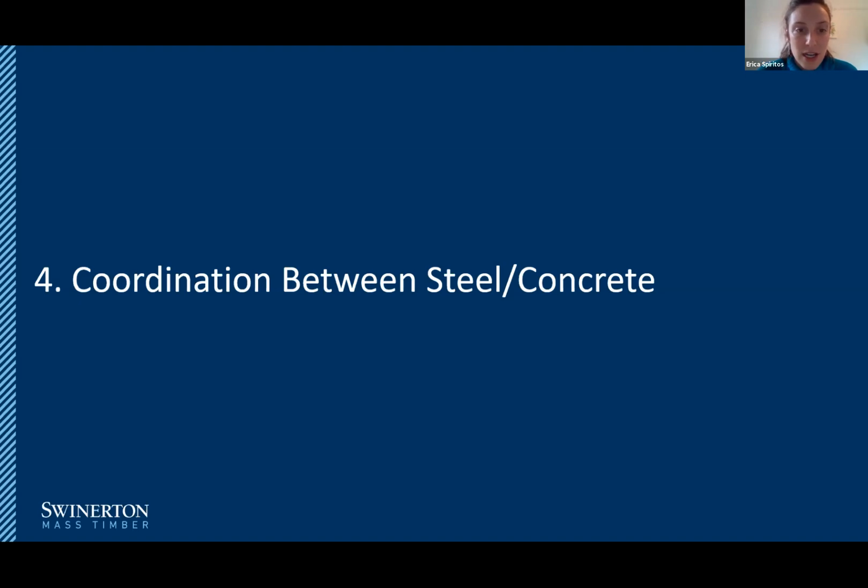And then another question, I noticed a CLT member at Katera in Spokane that resembled a double T concrete member. Could it be? Yes, you're right. You saw that. That is what we would call a ribbed CLT panel. So, imagine like a 10-foot wide by 60-foot long panel with 2 glulam beams running underneath the panel, lengthwise down the whole panel.